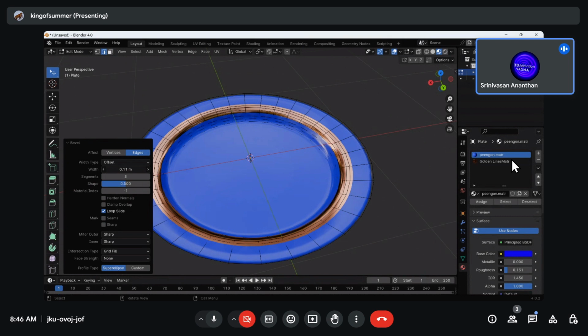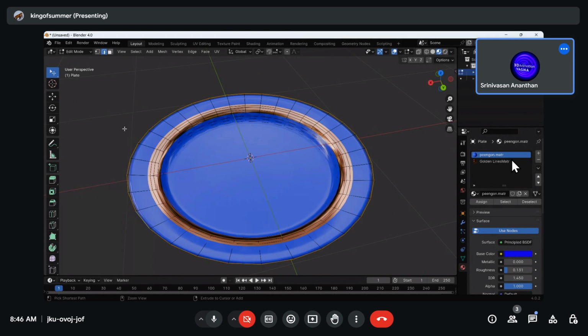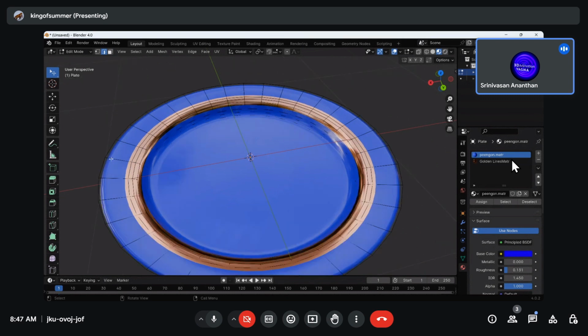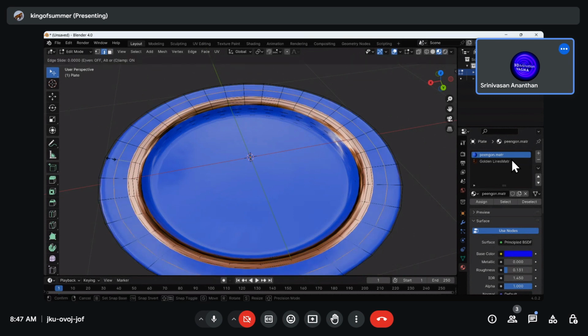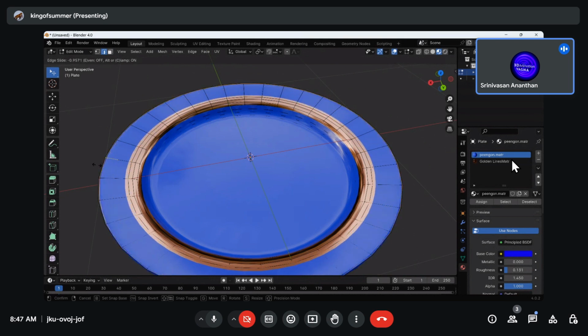Okay, it is not creating, I think. No, undo, it is not creating. Press undo, one more undo. Enough. Now we have to add it, that is the only way. Keep your cursor on the same edges, a little more inside the plate, slightly inside the plate. Now Control R, exactly there we should add. Now press left mouse button and bring it a little outside. No, not this much, a little more inside. Enough. Left mouse button, one click.